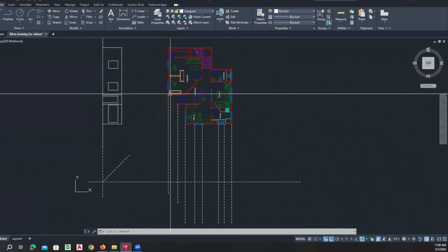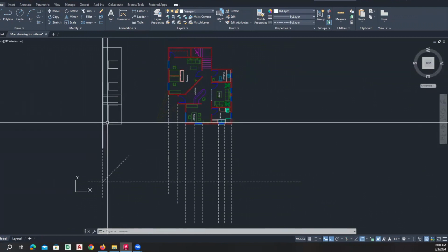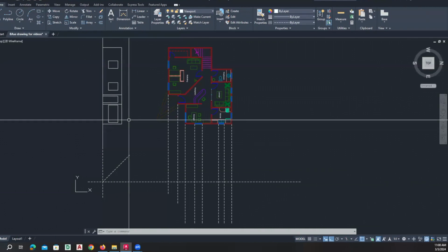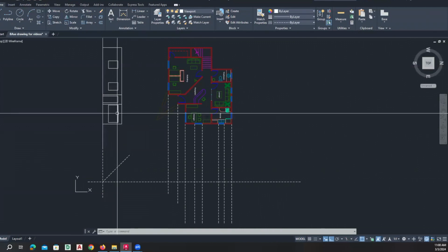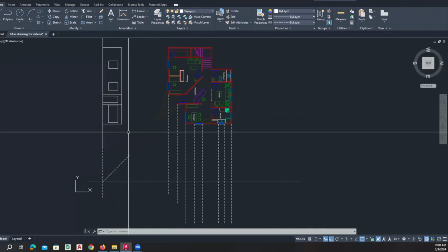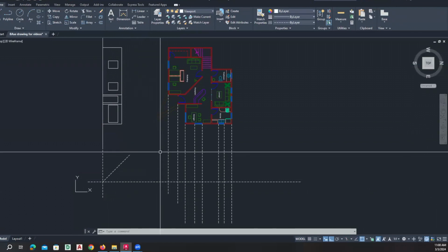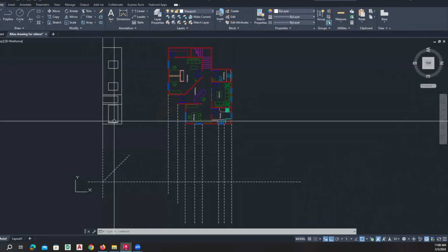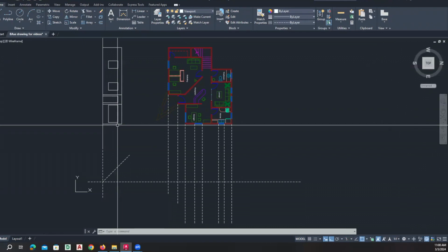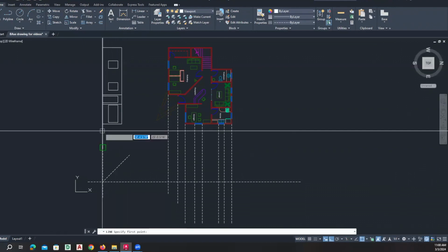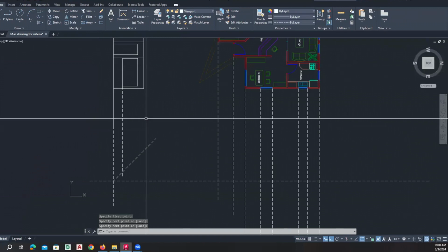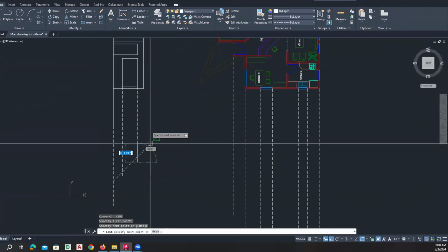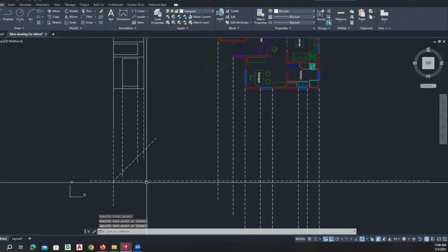Now, what that allows me to do is not only project information from the plan, it will allow me to project information from the adjacent elevation. So we measured before the height of the sill, the height of the window, and the roof line. We really don't need to offset those same dimensions from here if we've already done it once before. Now, this is a fairly simple drawing, and there's only a couple lines that we would have to do this, but most drawings are going to be a little bit more involved. So for here, we're going to project from this elevation down to that 45-degree line. Same thing with this point, down to the 45-degree line, and down from the roof line to the 45-degree line.